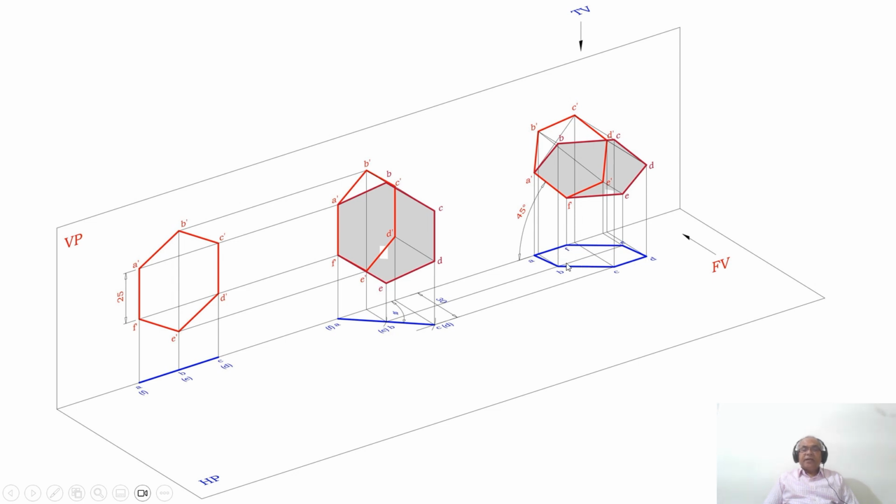So this is how you will be able to analyze this in 3 dimensions. Here the length you have is the true length and the inclination given is also the true inclination. Therefore, you rewrite the same sketch by rotating this lamina by inclining it at an angle of 45 degrees with respect to HP.